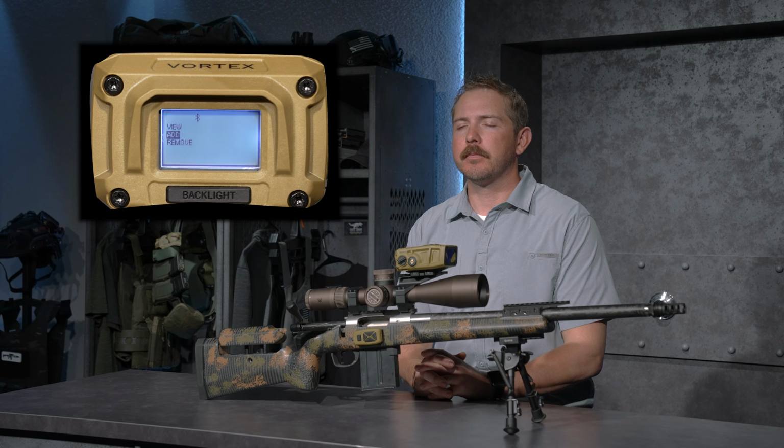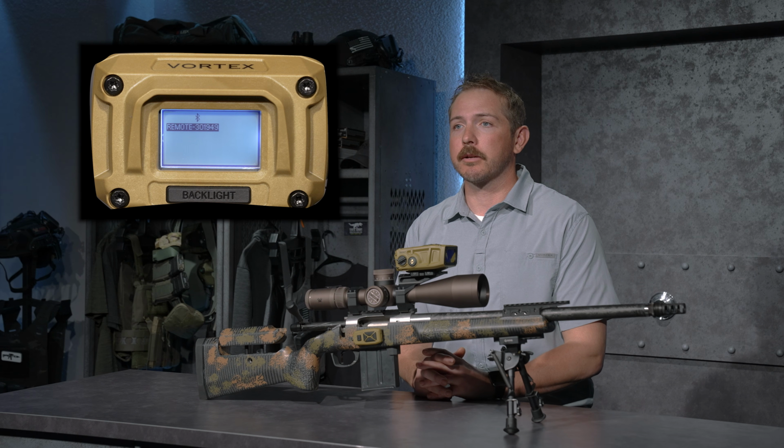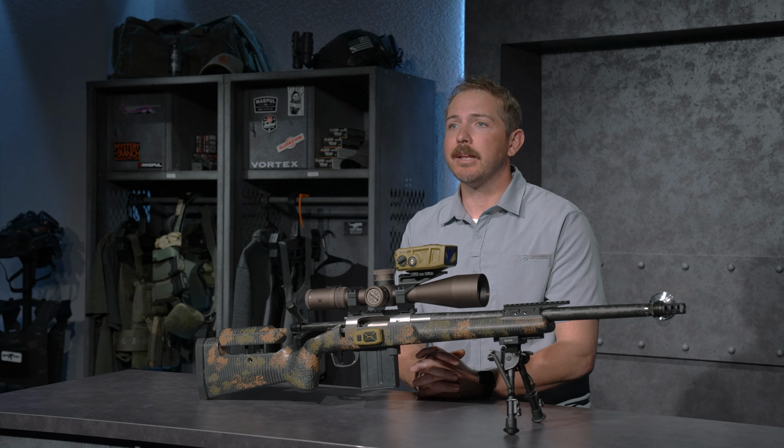The Add screen is where you can add devices to your network. The Impact 4000 will automatically find all compatible Vortex Relay Network devices that are turned on and within Bluetooth range, and are not already connected to another network. Select the device from the list that you wish to add. When the new device joins the network, if the profile or range cards are different, you will be asked on both devices which device's information should be used. Repeat to add any additional devices.